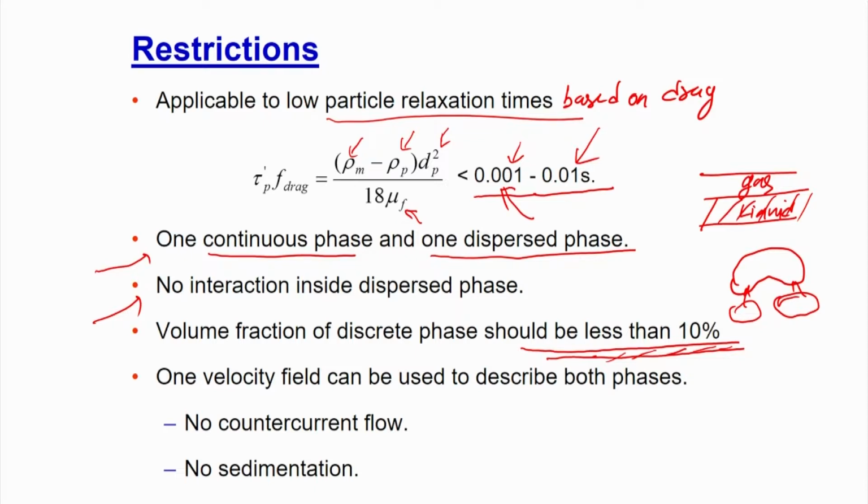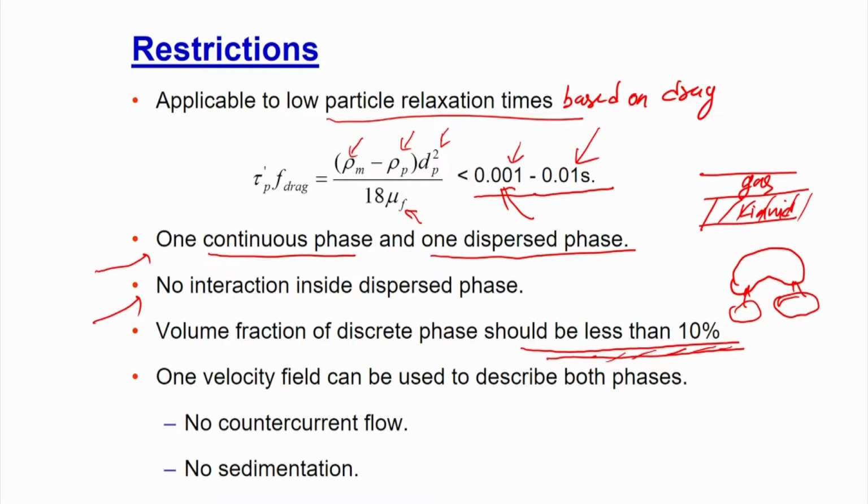One way coupling cannot be used, you have to have two way, three way, or at least four way coupling. That is why here we are solving just one way coupling, solving the equations of both the phases coupled only through the drag. And that drag is also not part of the main equation. We take drag into account in the slip velocity. So, that is the major limitation: if your discrete phase fraction is more than 10%, the ASM model or algebraic slip model cannot be used.